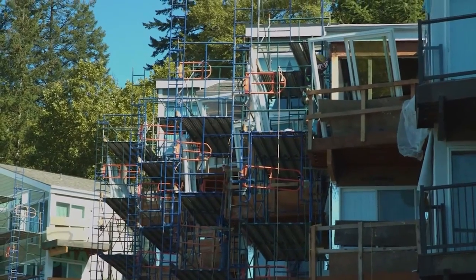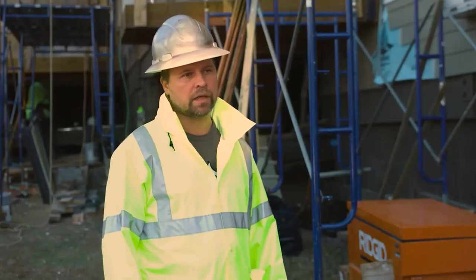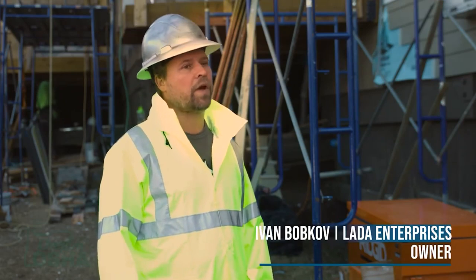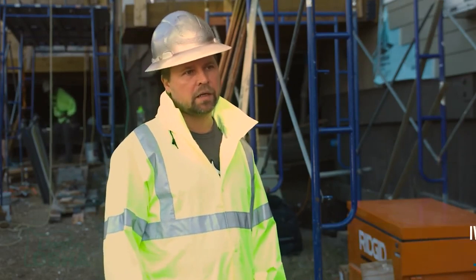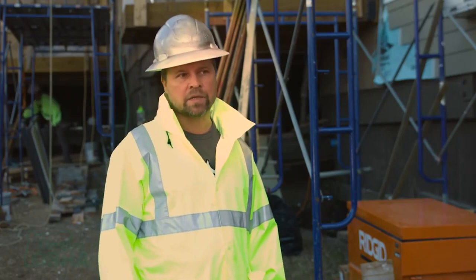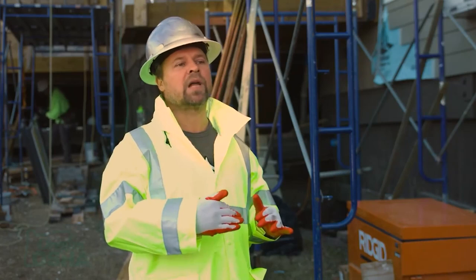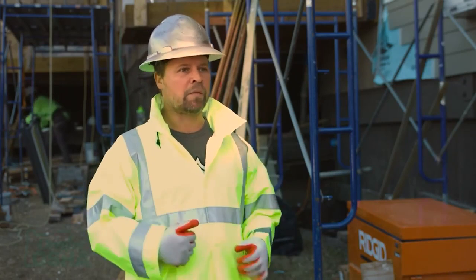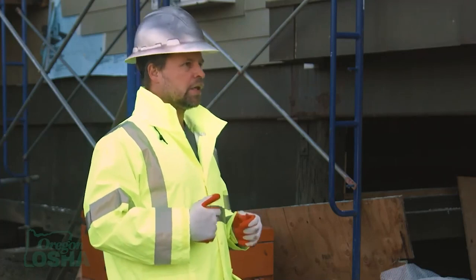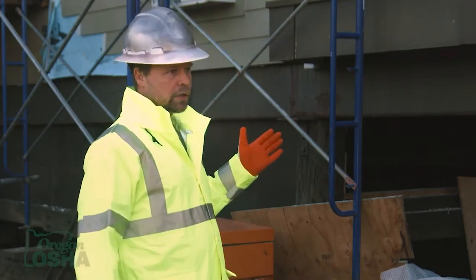At this building, we use anchorage to attach our linear ropes for our harnesses, and it's set up on a roof. Each ridge of the roof has anchorage in there. On this particular building, it was already pre-installed, but we verified it was installed correctly, because you don't want someone to have mistakenly installed it just over plywood, where it will just rip right off. You want to make sure there's solid framing on both sides and the proper fasteners. You don't want to just install it casually, and that's what they tell all the guys too.